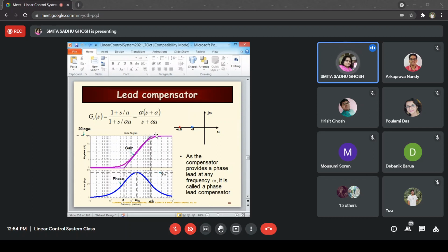Okay, so here on this plot you find that there are two plots. I had used MATLAB for doing the plot, that is why the actual plot also has remained, but as far as you are concerned and as far as designers are concerned, the asymptotic magnitude plot is sufficient, and in fact that is the plot which is used for designing, knowing very well that the exact plot would be following the asymptotic plot apart from the values at the corner frequency.